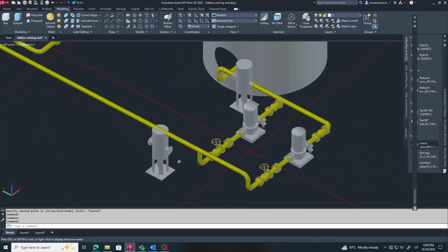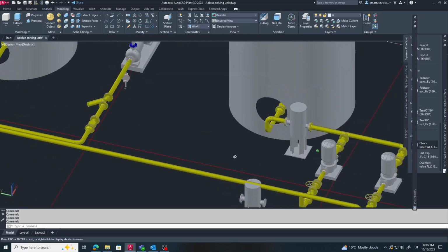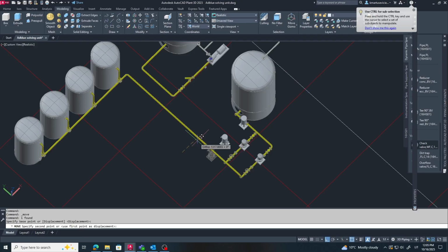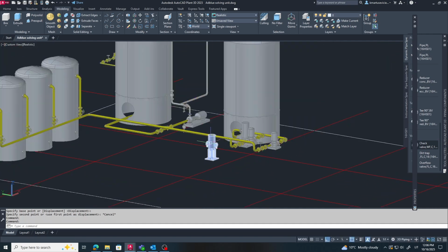We can use the same type of filter housing, but keep in mind that the mesh inside this filter is different. The mesh size defines how fine the filtration is, so even if the filters look identical, their function in the process can be quite different. Let's connect it to the main line.